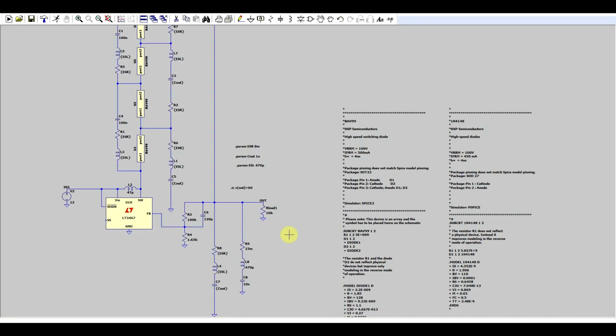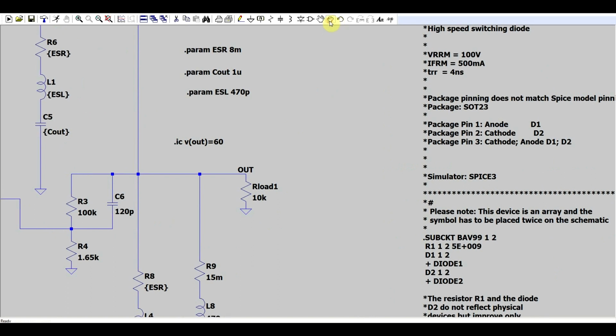Now on the other hand, another thing that is important to remember is that usually your load will not be directly connected to the output of the supply. There will be a certain length of trace and then your load will be somewhere else on the board. And if we remember our talk about parasitics, we can consider the length of wire going to the load as having a bit of resistance and a bit of inductance. So let's say about 5 nanohenry and 100 milliohms of resistance. So this is a very thin wire and it has a bit of inductance.